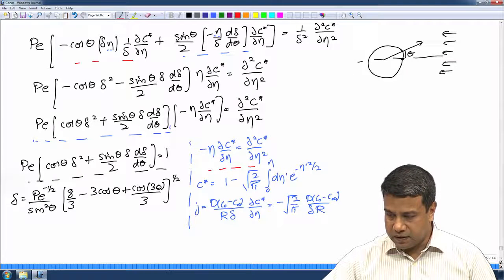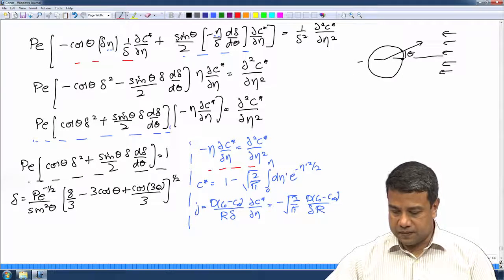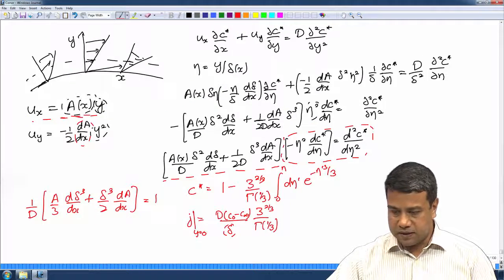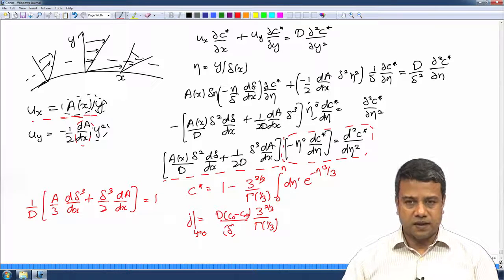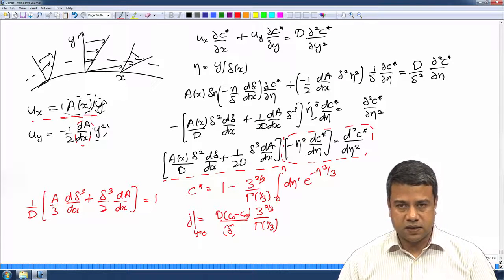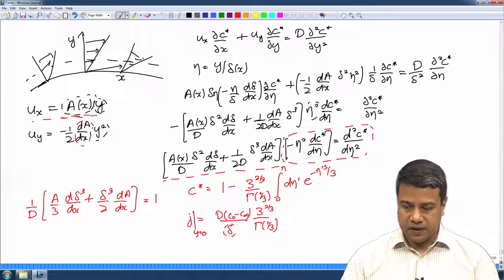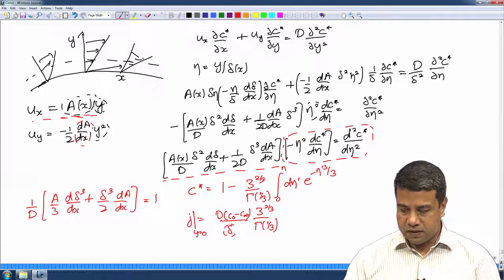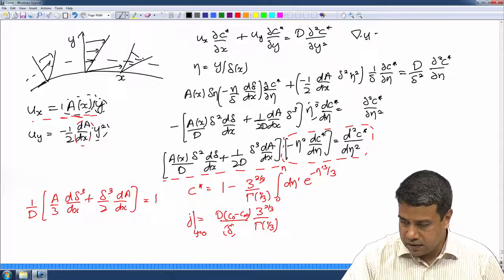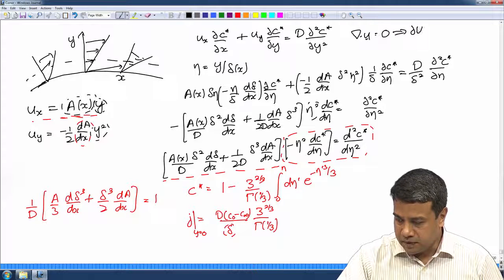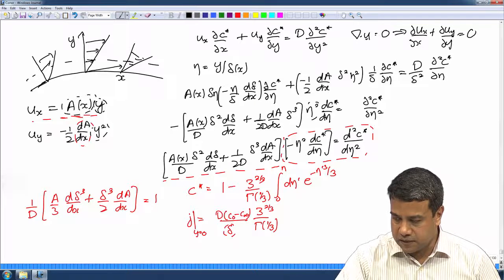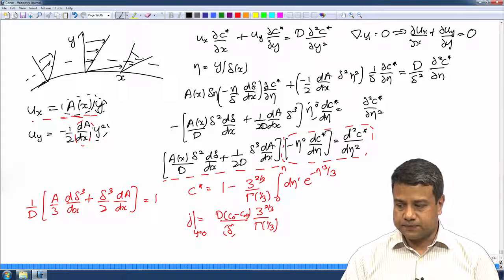And that is true even for the flow around a bubble. We had solved that problem as well and got the correlation for the Nusselt number versus Peclet number. And then last class I had briefly shown you that all of these can be placed in a common framework. The flow is in the x direction, the streamwise direction, and the cross stream direction is y. There is a condition on the velocity that the divergence of the velocity is equal to 0, which implies that partial ux by partial x plus partial uy by partial y is equal to 0, in 2 dimensions.